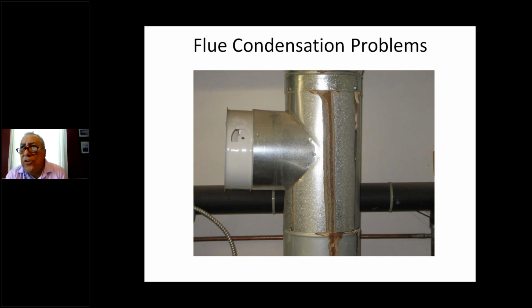I remember we had great numbers. We were approaching 90%, like 88% efficient. We had low stack temperature and great efficiency. Well, whoop-de-doo, look at what I did. I came back a year later, and this is what I saw. What we ended up doing was sacrificing some of that efficiency by raising the stack temperature to stop the condensation. This was a 1 year-old job, so you don't want to condense in the chimney.